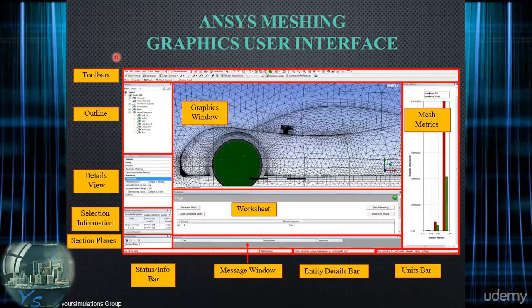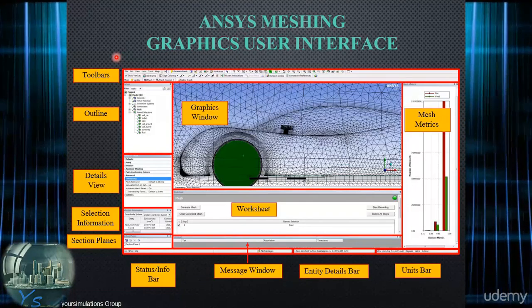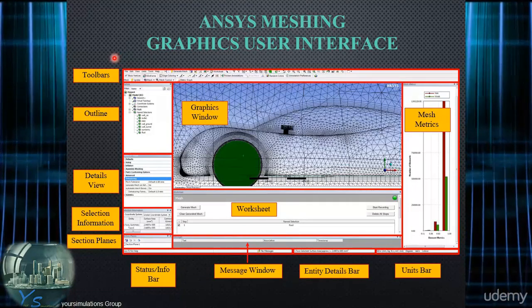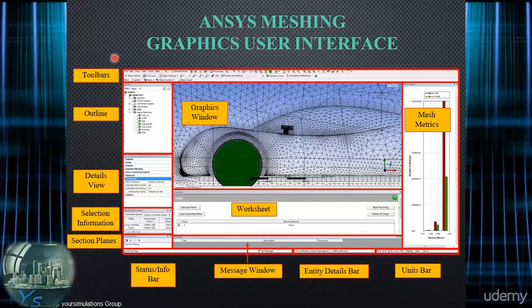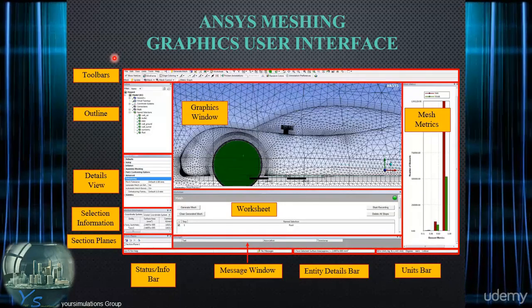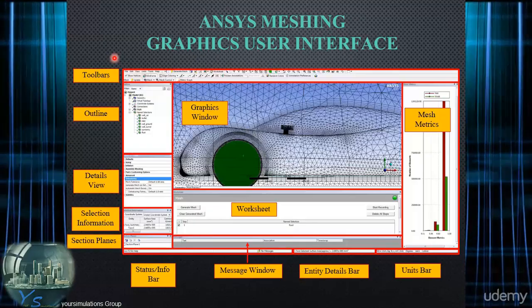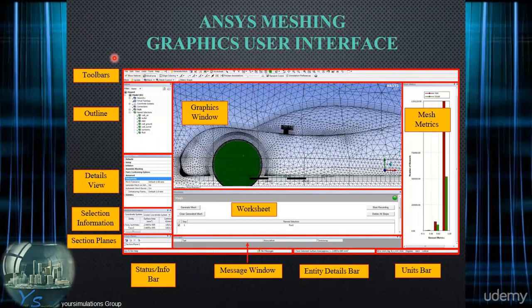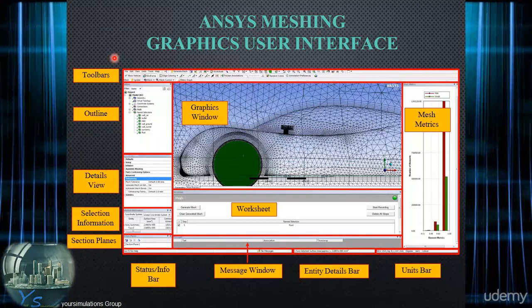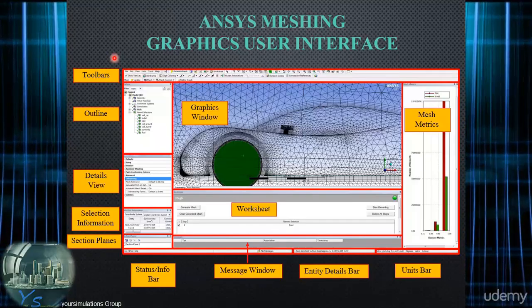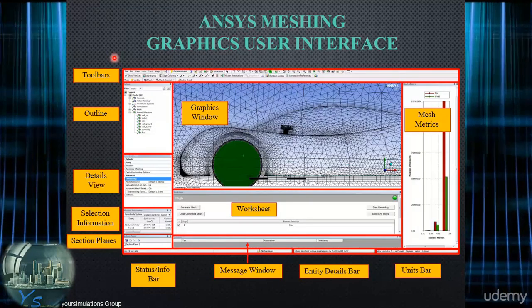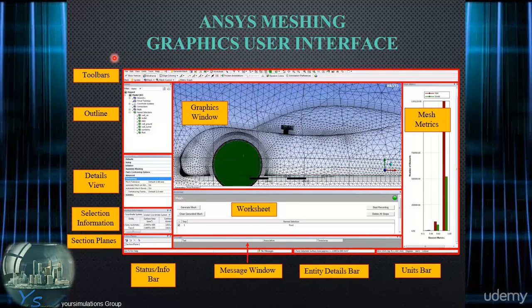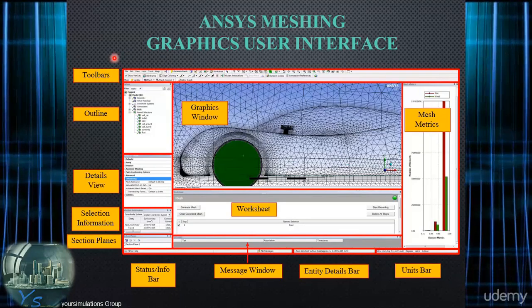However, sometimes it happens that the layout cannot be restored by that function. In that case, we can delete all settings for all ANSYS products by deleting the folder at these locations. This will eliminate all settings except the licensing information. Of course, we should be sure that no ANSYS application is running before deleting the folder.